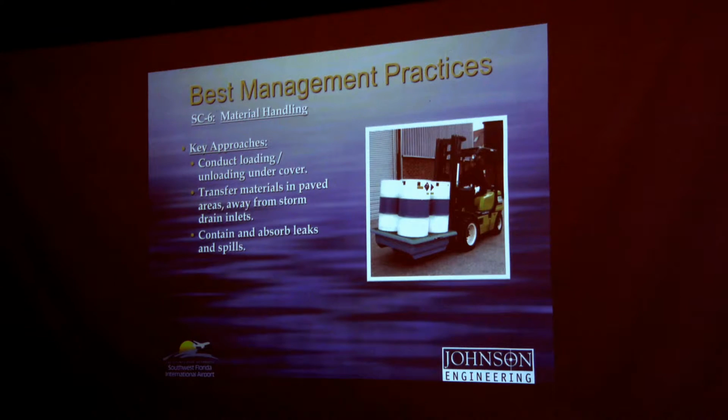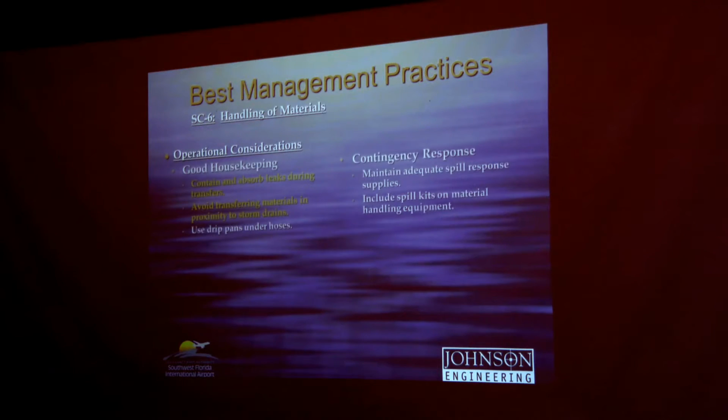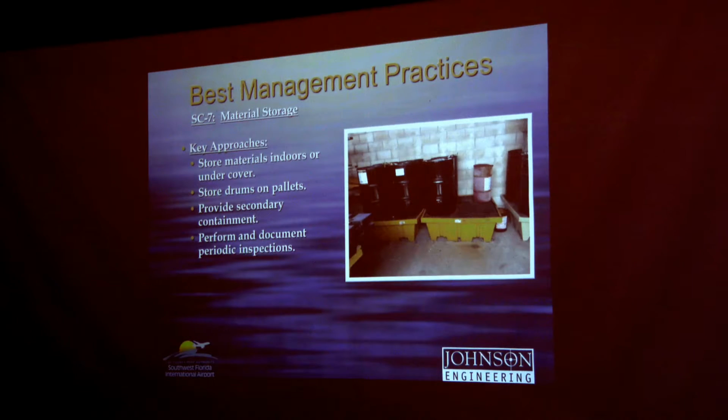A spill that happens on asphalt or concrete, 50 gallons, even 100 gallons, is a lot easier to deal with and clean up than the same spill that is spilled right next to a storm drain or a pervious surface. So please make sure that these material handling activities are performed away from those storm drains. Additional operational considerations include using drip pans where you can, maintaining spill supplies, and including spill kits on the material handling equipment themselves.